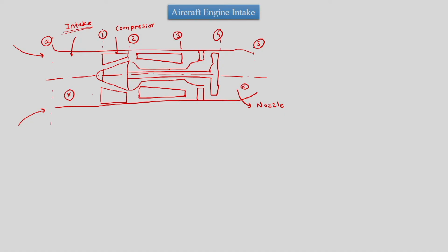The intake should also be properly aligned so that it has the highest performance at different angles of attack and at various operating conditions like maximum thrust, low speed and high speed. For that, the intake should always supply a given mass flow rate of air with the designed or required pressure to the compressor.